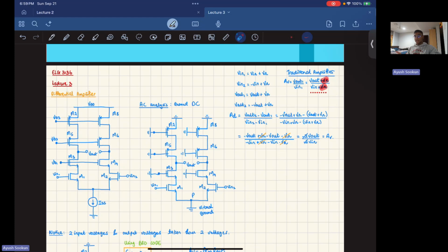You can't have an inaccurate device, because that would throw off readings, and you need very precise measurement for the heart, because it's sometimes a matter of life and death. So having a differential amplifier is a great application in that case, because it gets rid of that noise completely, and you can see your signal better.